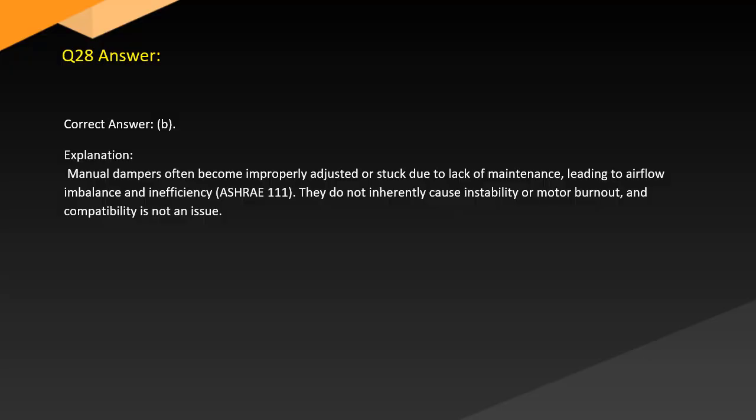Answer. Correct answer, B. Explanation. Manual dampers often become improperly adjusted or stuck due to lack of maintenance, leading to airflow imbalance and inefficiency. ASHRAE 111. They do not inherently cause instability or motor burnout, and compatibility is not an issue.